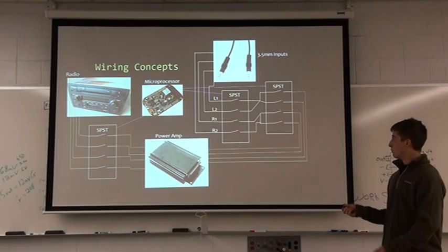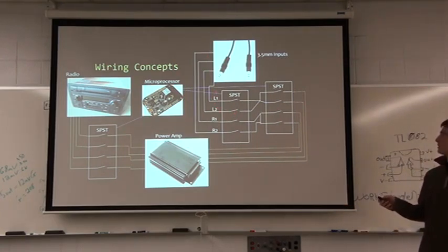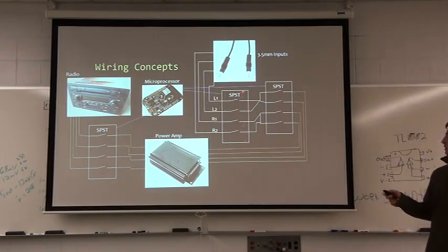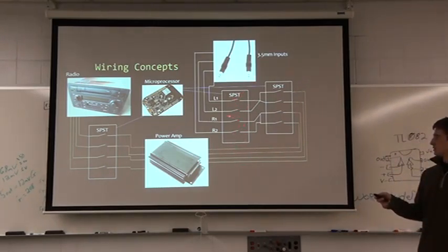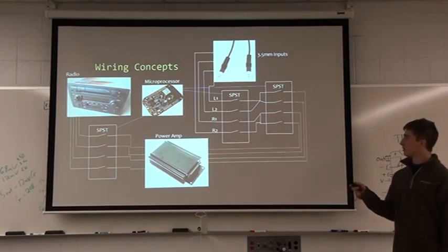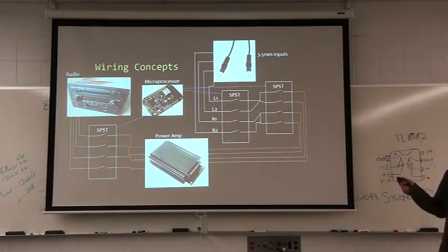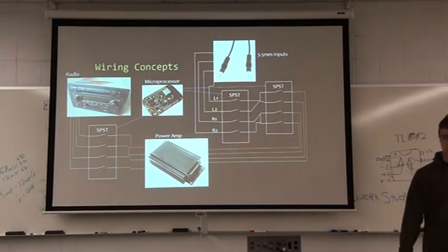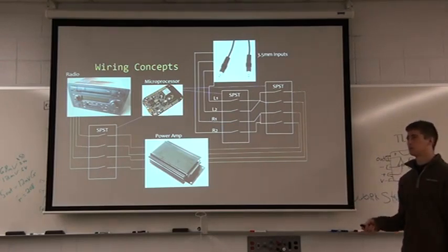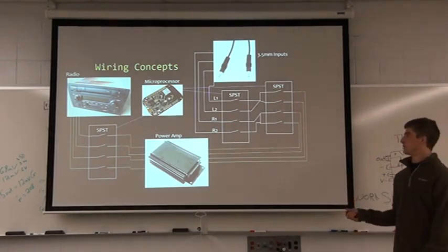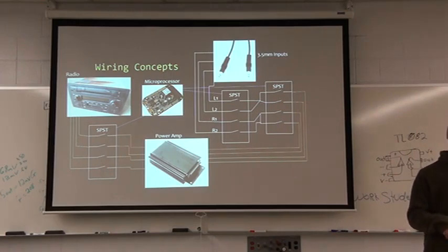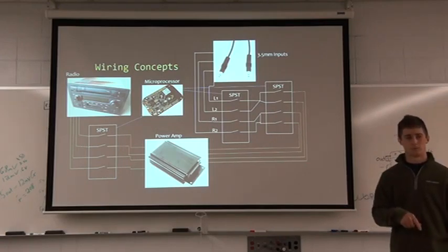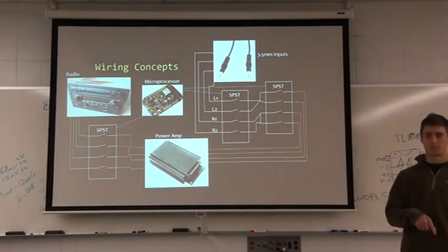Then when there is a phone call on one of the audio jacks up here, the microprocessor will switch the corresponding switches for that particular audio jack, close all of these switches to the powered amplifier and open those. The other audio jack is for an auxiliary input, and I can push a button on the board for a kind of manual override, so that it will switch to that input.